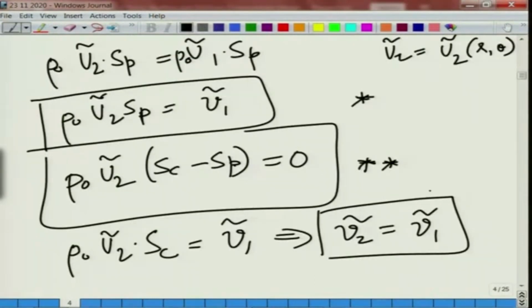no matter even if we disregard the higher order modes, if the frequency of excitation is less than a certain frequency, those modes are cut off, that is to say they do not propagate. Only beyond a certain frequency they become cut on, or they start propagating. So basically, as long as we are well within the first cut on frequency, no higher order modes are propagating, only the planar waves are propagating. Higher order modes, as we recall from lectures 3 to 5 of week 2, have variation across the cross sectional area.